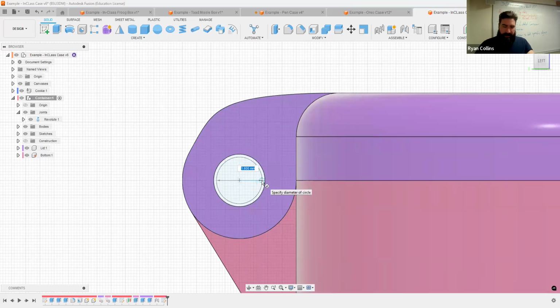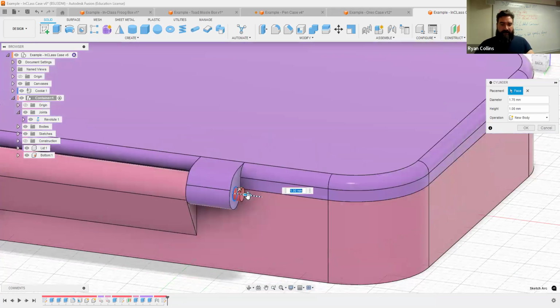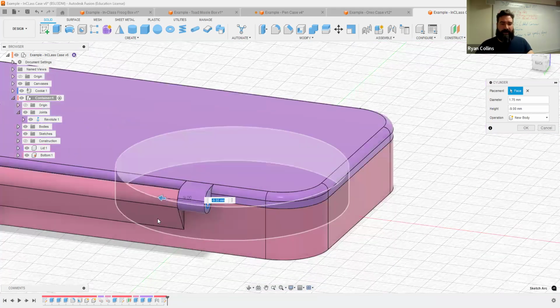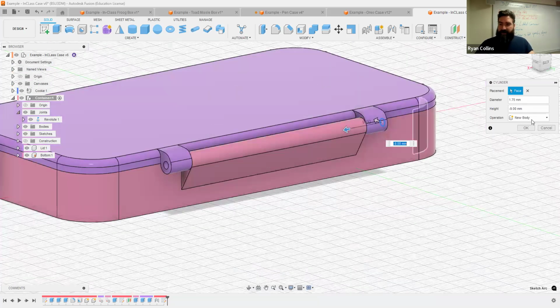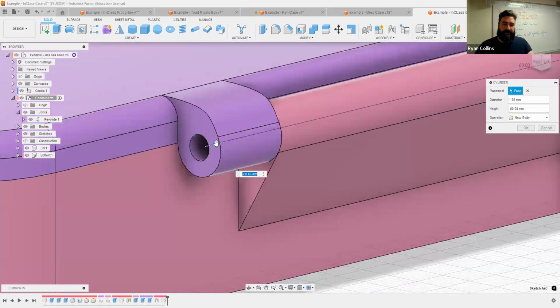Now, as a placeholder, because the filament we're using is 1.75 millimeters, select there. You see that tiny little gap. That's what we need. And again, yeah, I could drag this all the way, but I want to be lazy and let the program do it. So for length, if I had left it at 0, now it's not letting me select to the face. Oh, that's frustrating. Well, we'll just have to draw it all the way down. I was hoping I'd be able to just use that. So you could make this flush. You could technically print this out a little bit, make it a little bit longer.